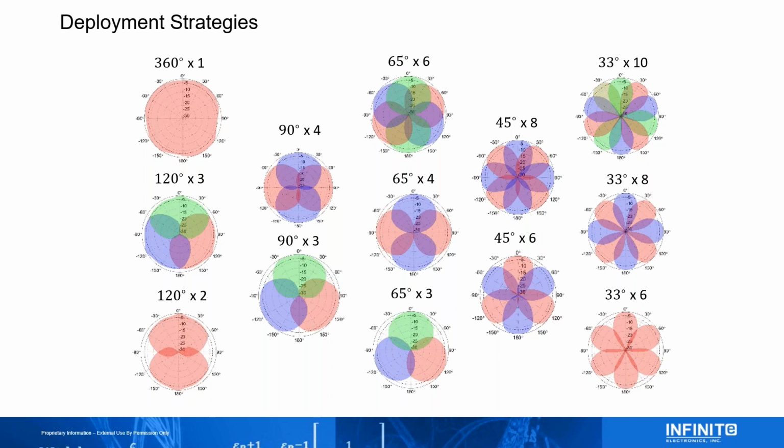So you're better off using a flat panel antenna or a parabolic antenna or a grid antenna or even our Yagi antennas would be a much better option for you. You want something highly directive.